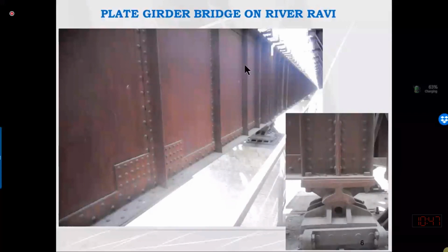Okay, here at this point, you can see that in steel structure we can actually provide a hinge. So this is a hinge. This point cannot translate in horizontal and vertical direction, but due to flexure, it can rotate. So this is a typical hinge support, and here you can see that they have used one, two, three, and four angle sections as a bearing stiffener.